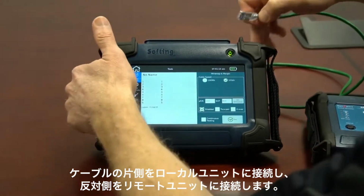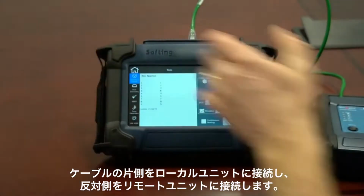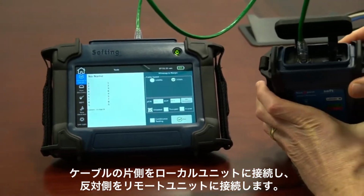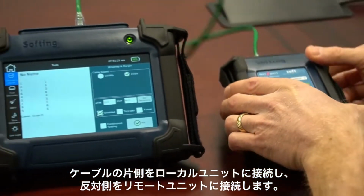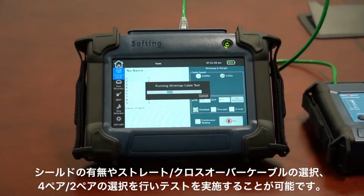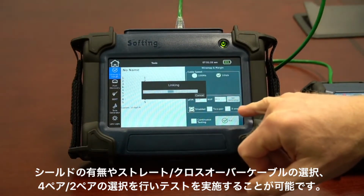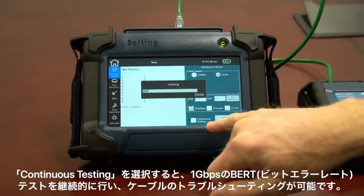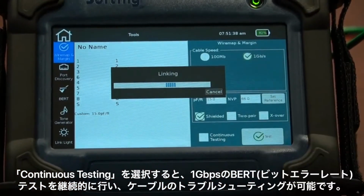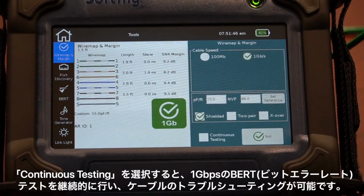I need to connect one end of the cable to the local unit. I need to connect the other end of the cable to the remote side. All right, and then I just need to run my test. There are some settings that I can set up if this is a shielded cable, a 2-pair, a crossover cable, or if I want to do continuous testing. I can run a gigabit per second bit error rate test continuously, and see, if I'm troubleshooting the cable, I'm looking for intermittent problems and that sort of thing.